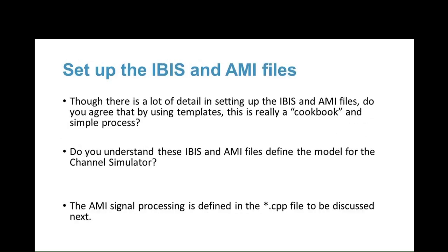So we've gone through the setup of the IBIS and AMI files, and though there's a lot of detail in setting it up, do you agree that by using templates, this is really a cookbook and simple process? Do you understand that these IBIS-AMI files define the model for the channel simulator? The AMI signal processing is defined in the CPP file. That's the C++ file to be discussed next.